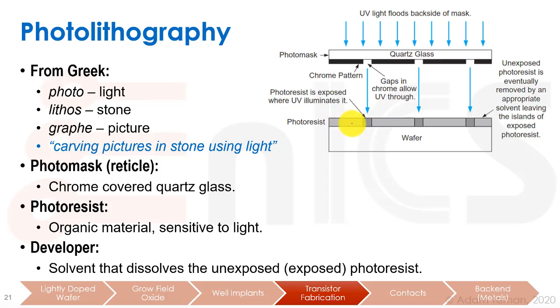Photoresist is the organic material that we have on the bottom here, the purple thing in my pictures before, and it's sensitive to light. So for example, when the light comes through, it will harden these areas, and then we can wash away the parts that aren't hardened, and we're just left with these pieces of hardened material. It can also be the opposite, where everything gets hardened except for the places that were exposed, and then we'll wash away just them. Anyway, after doing that, we can do all kinds of things to our substrate that's now covered with the photoresist.